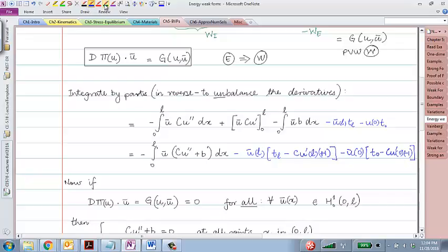All of this is nothing but the method of weighted residuals form of the weak form. We started with the energy form, we did minimization, we came to the PVW weak form. We did reverse integration by parts, so I'm going to call this RIBP, reverse integration by parts, and we are back to the method of weighted residuals form of the weak form.